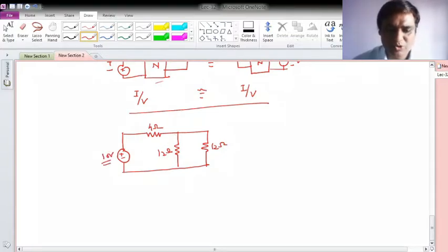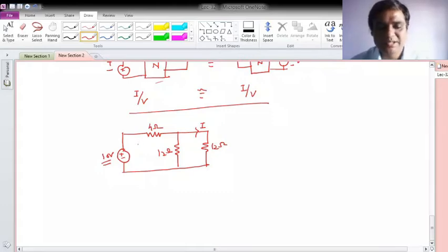Okay, so what is to be done? This voltage has been given and I have to obtain the response. So suppose this is my I. First time, I'll find out the ratio, that is I divided by V, and next time I'll change the terminals. So this voltage source will be here and this 4 ohm will be the load, and I can obtain the current here. And let me check what this ratio is.